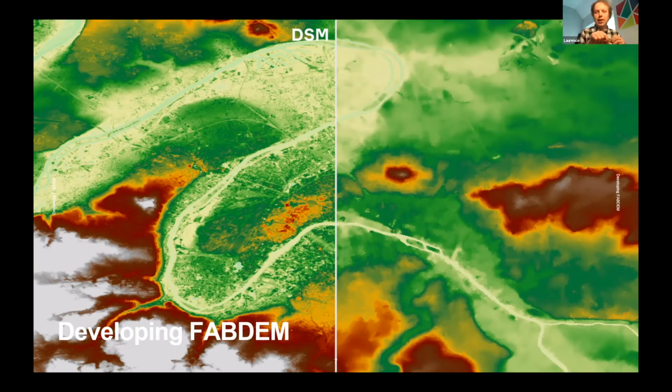Each of those little squares has an elevation value, and this is usually above a datum, so usually mean sea level or a national datum. So imagine this covers the whole world. These little grids are what are used in the computational flood models to give something like what was just shown in the last slides from Gavin. Next slide, please, Gavin.